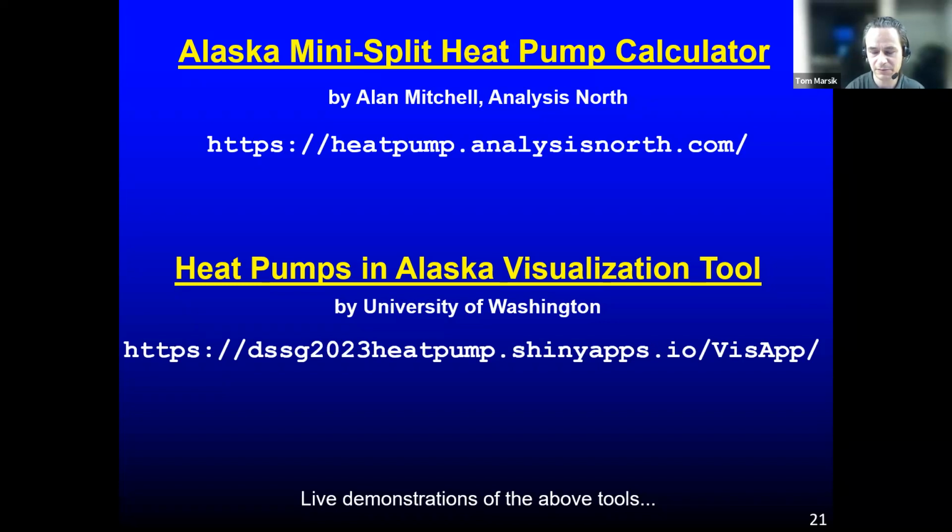So bear that in mind when you see ads for super efficient electric space heaters and such. Bear in mind that actually they all have the same efficiency, which is 100%. There can be, of course, differences in how you use them in the space. If you have systems that really just provide localized service to where you are at your desk, for example, then that can impact the amount of energy you are going to use. But as far as the efficiency of the system itself, it's the same. It's 100% efficiency for any electric space heater.